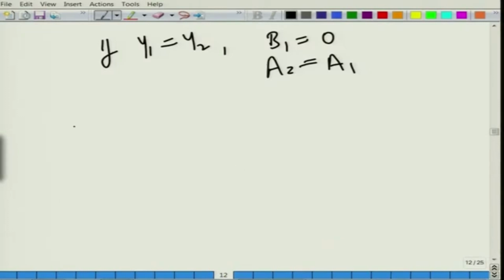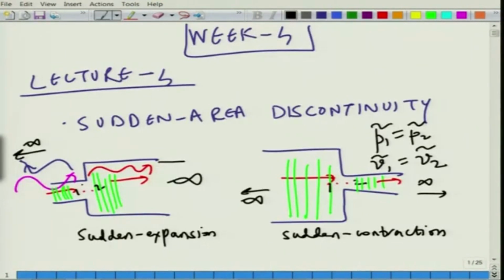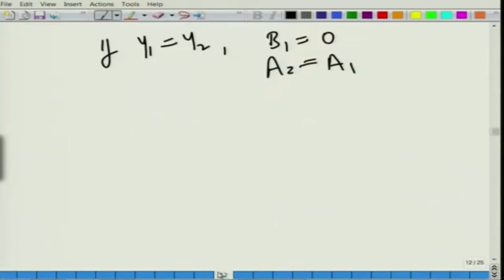If we were to derive a general expression for that, let us derive the acoustic power that is incident on the muffler. If you have a system like this, the power incident at point 1 is the acoustic power carried by the wave front A1. It is the incident power expression, if you recall from our last lectures. This is point 1, this is point 2, so this is incident at point 1.